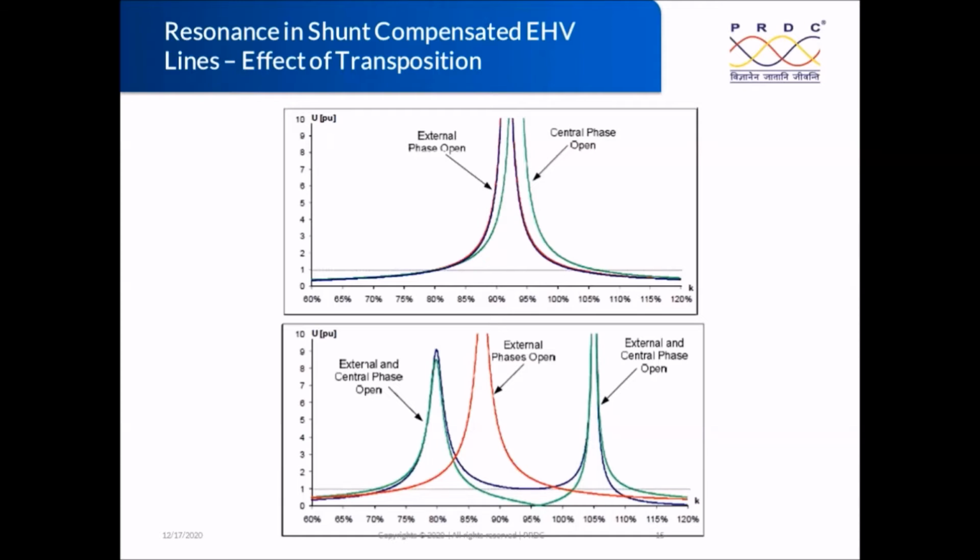Generally, in practical conditions, people will go with the trefoil configuration, because in trefoil the conductors are placed next to each other, and it requires very minimum right of way when you compare with a uniform placement.